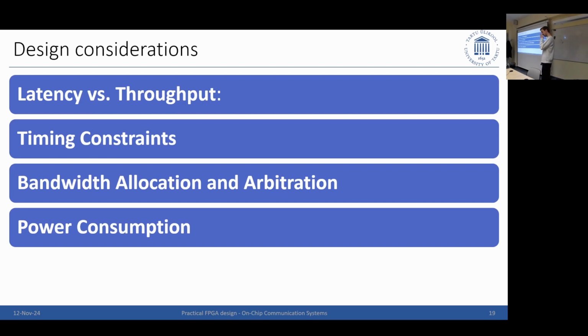When we then have these different options, we have a lot of different factors. What do I use? Where? When? How do I use it? What implementations do I use? In general, this is a beautiful tool to standardize your interfaces and your workflows. So ideally, you write once, or you get a very nice AXI interface from somewhere, and this will make it perfect, because then you have the same AXI implementation everywhere. You know that this one is very optimized for timing, resource utilization, and so on. So if you have a thought out concept, you will have very good latency.